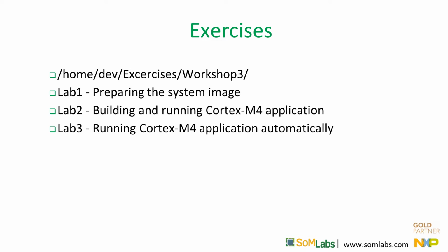At the beginning, we will build a new system image after applying the prepared patches that launch Cortex-M4, and we will launch the application intended for this core. Finally, we will prepare a system image in which the application will be launched automatically at system startup. The necessary resources for all exercises are in the Home Dev Exercises Workshop 3 directory on the virtual machines disk.